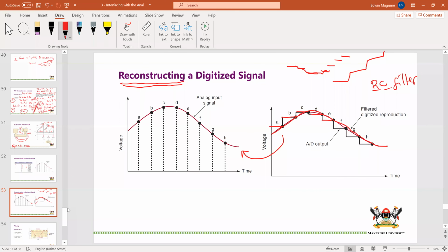It is impossible to ensure that they are similar; we can only bring them as close to each other in similarity as possible. And the only way we can do that is by increasing the number of bits. So if you are using 8 bits, use 10 bits, use 12 bits. The problem with that is that you have more bits to store, so there's some kind of trade-off for you to consider. Any questions before we move to something else?